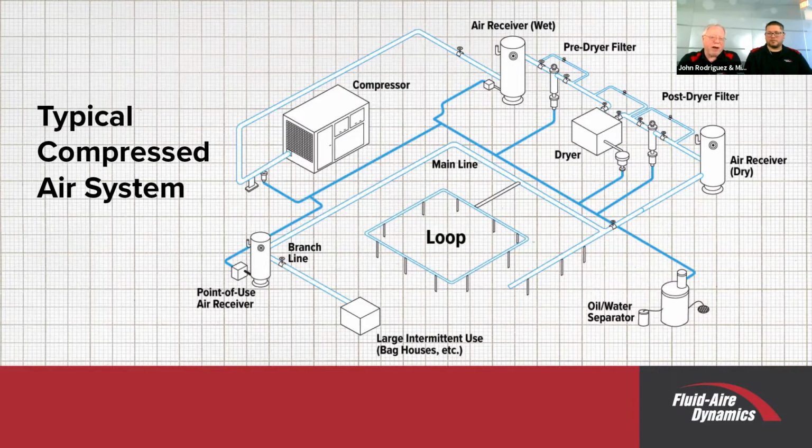So by air coming from two different directions, two things happen. Number one, nobody's going to rob that person of air. But number two, you've actually doubled the size of your airlines, or 1.5 times the size of your airlines. What I mean by that is there'll be less pressure drop because we've increased the amount of piping leading to any one point.